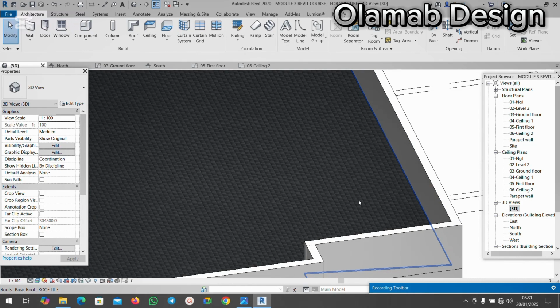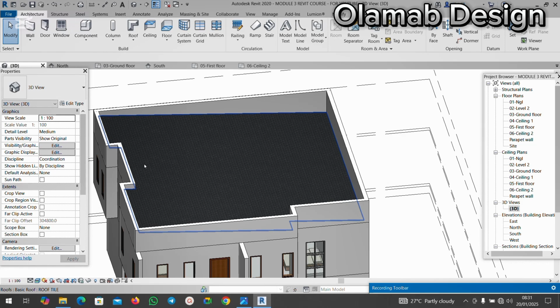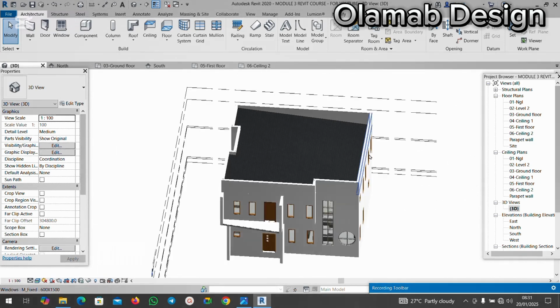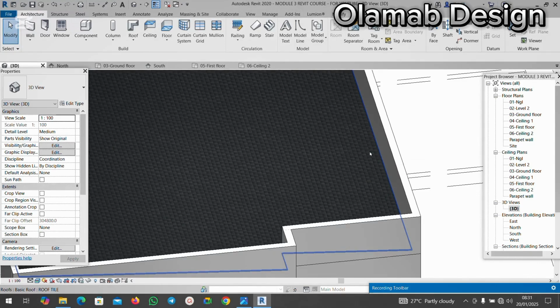We are going to be having it there, and which requires a slab. It's going to require a slab at this end, because as it's sloping down to this side, the water is going to drop on that slab. Then there will be a pipe. Okay, there will be a roof drain that will take the water down. The pipe must have been inserted inside this wall. Okay, so to do that now, it means this roof is not going to extend to this wall.